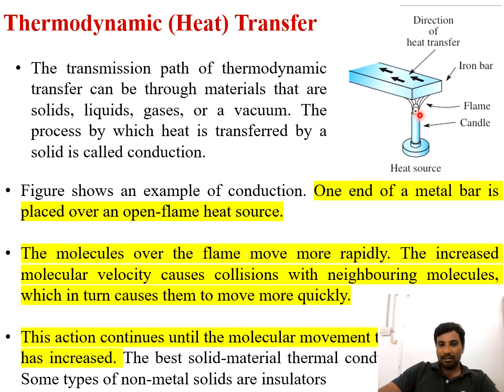One end of the metal bar is placed over an open flame heat source, and the molecules over the flame move very rapidly. The increased molecular velocity causes collisions with the neighboring molecules, which in turn causes them to move very quickly. This action continues until the molecular movement throughout the bar has increased. The best solid thermal conductors are metals. Some types of non-metal solids are